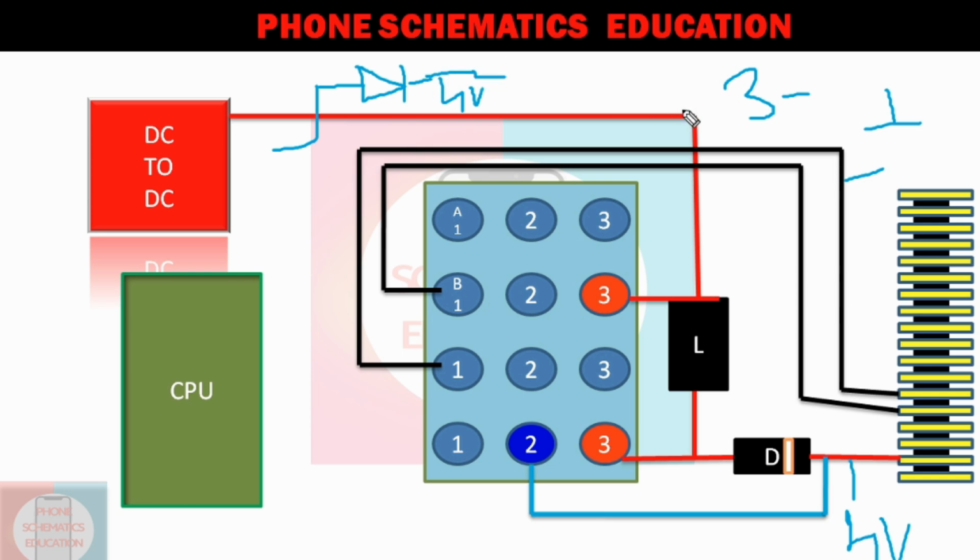When you connect 6 or 8 bulbs in series in a strip for more lights to glow fully, now if it is 4 volt and 6 bulbs, that means 4 into 6, 24 volt needed. If there are 8 bulbs, then 32 volt needed. But on the battery side, you will get a maximum of 4 volt on the VPH or V system line.